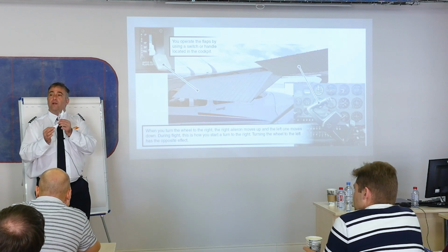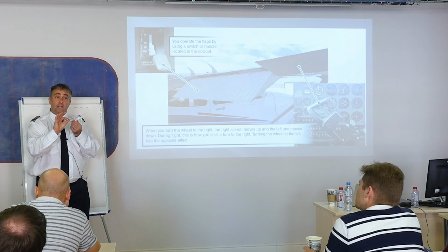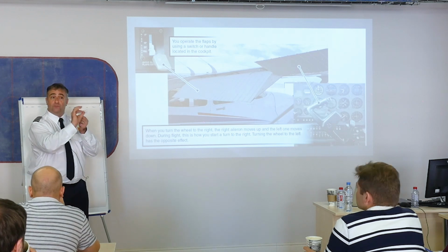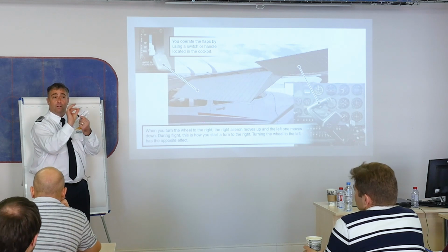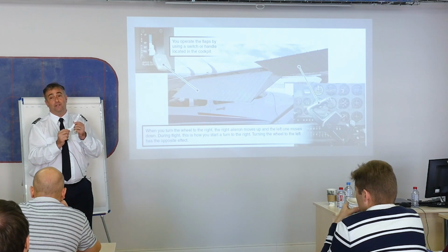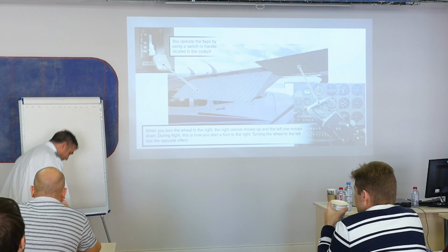Okay? And that's one of the ways that the engineers have designed this thing with the ailerons on the outside. Number one, it gives you the most amount of arm, or the most amount of power while you're trying to bank the airplane. It also gives you the maximum controllability while you're close to a stall. So that's why the ailerons are on the outside.